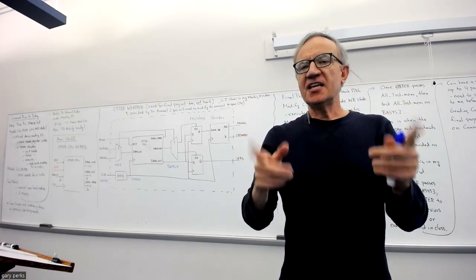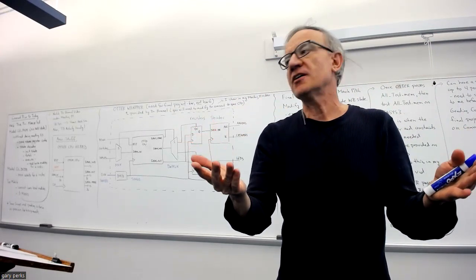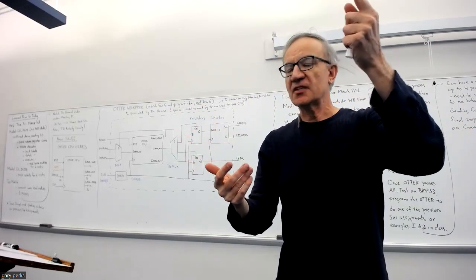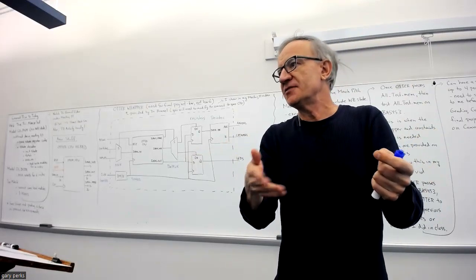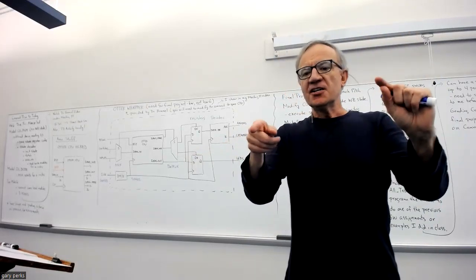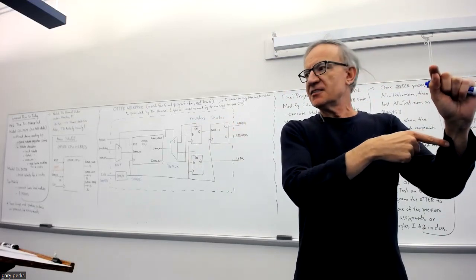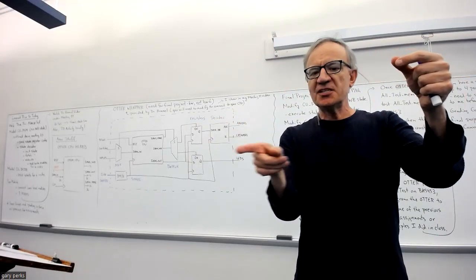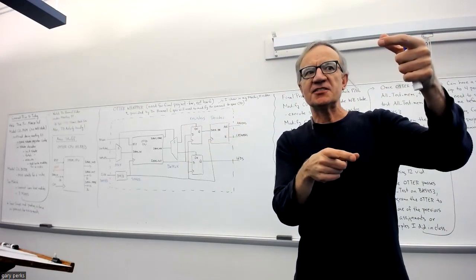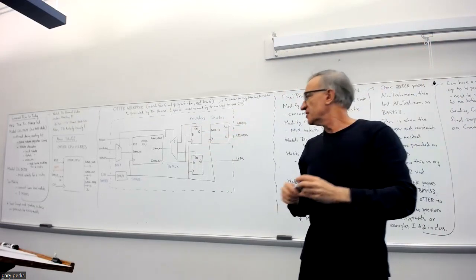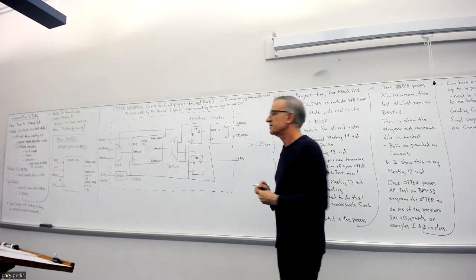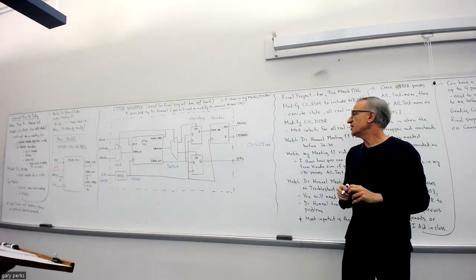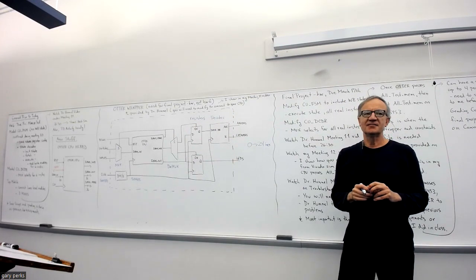Some instructions take 16 or more tests before you can say it's good. Other instructions may only take 4 or 5 tests before you can say it's good. So sometimes you'll see all the LEDs light up across and it increments. Other times you'll see maybe 6 LEDs light and then it increments. You should see the 7-segment display increment from 0 to 24 hex. What's 24 hex in base 10?